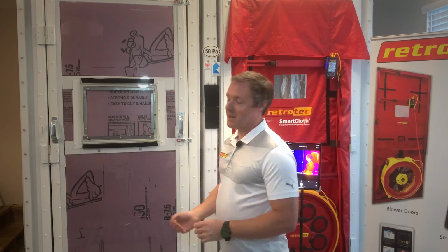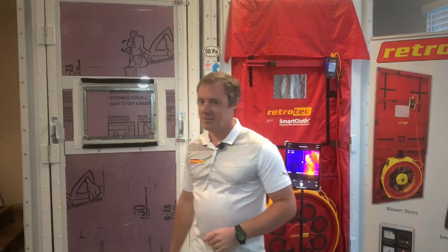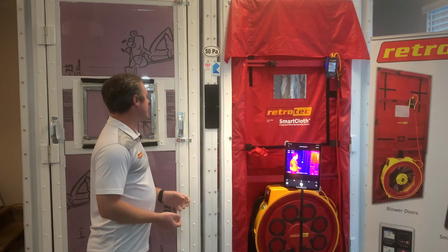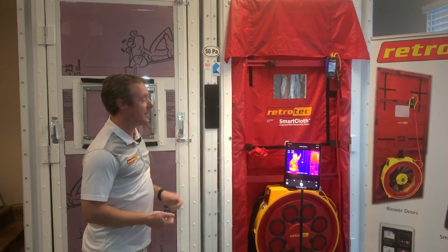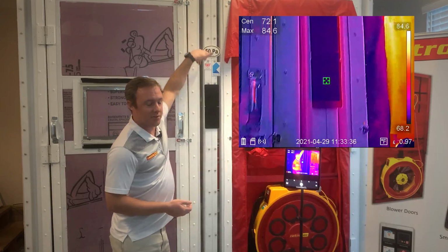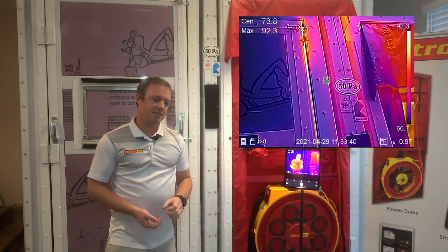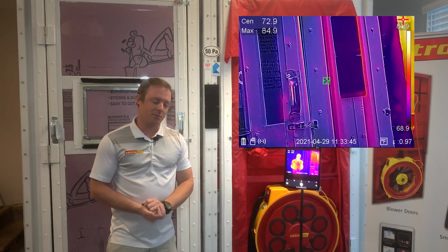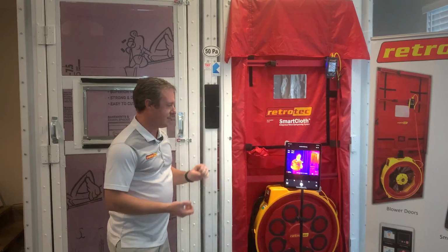And there are some areas that don't have it, such as these small spaces here in the front. You'll see that we can tell some differences here between what's air leakage that we can see coming out of this poorly sealed panel here versus thermal bridging that we can see here that's kind of a lighter glow. So that's one thing that I always recommend: it's important to be able to differentiate what you're actually seeing in a thermal image.